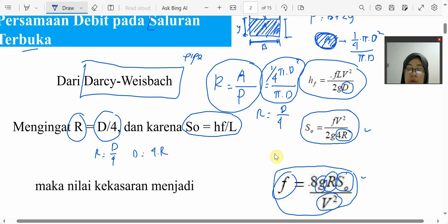Also, if I say what impacts the velocity, if we consider the friction factor and also the open channel characteristics, we know from this slide, from this big picture, that the parameter that impacts the velocity is the hydraulic radius, okay?